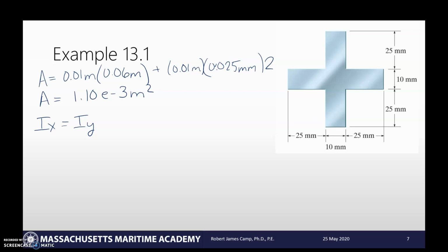If I have a circular shape, I'm usually not going to be using the parallel axis theorem because it's just going to be one circle. It might be a hollow circle, so we take the moment of inertia of the outside, subtract the inside to find out what the ring is. But it's very unlikely that we're going to have a column that's a circle with a rectangle coming down. I'm not saying that can't happen, but it's pretty unlikely.